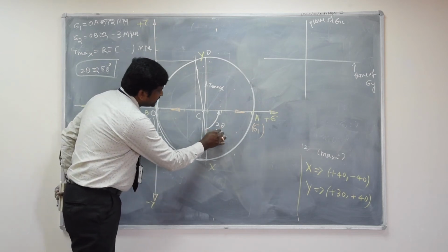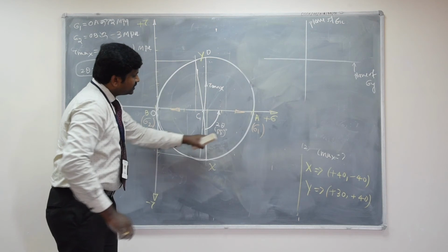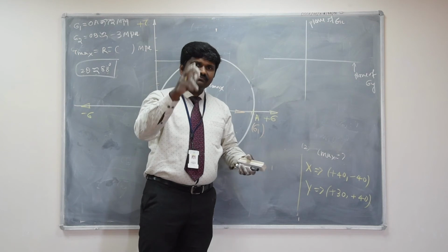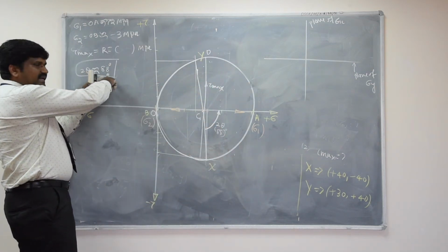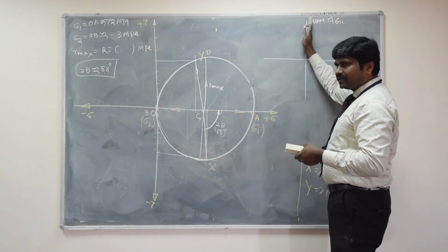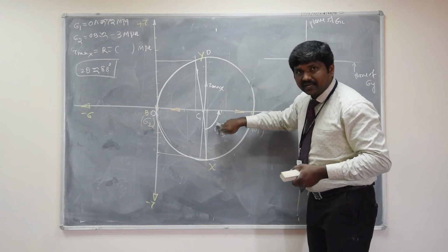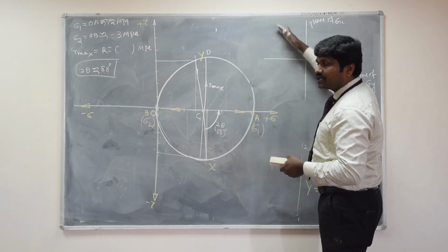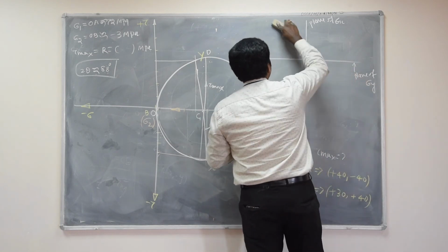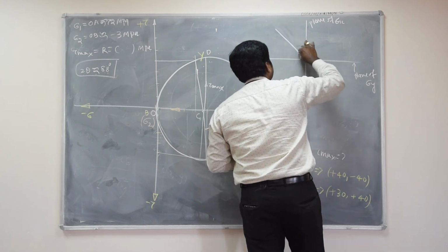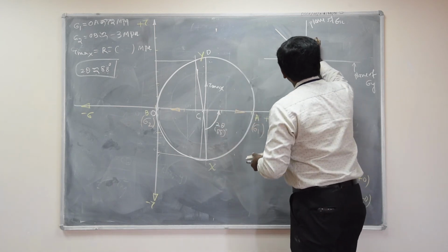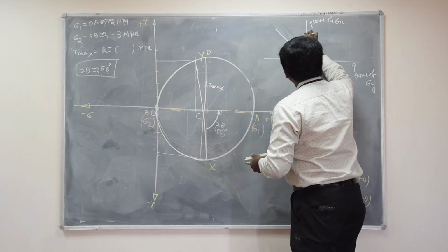This was approximately 88 degrees in terms of 2 theta. While reproducing this angle on the two-dimensional element, you have to take half of that because we need theta. So if it was approximately 88 degrees, take half of that, around 44 degrees. From the plane of sigma x, in whichever direction you measured the angle, in the same direction you rotate the element or draw a line. So it is approximately 44 degrees, in the same direction as you measured. This is theta.